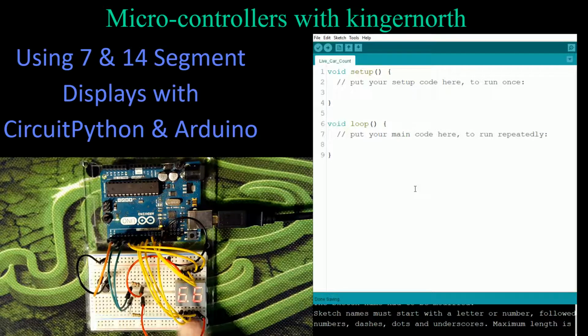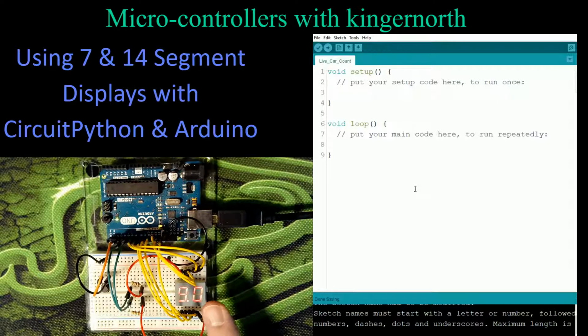And in fact, if you wanted to connect a resistor to every one of these other pins and then use a digit pin, theoretically you could control it. The problem is the current would be too high. So if I had to do the number 8, for instance, all 7 segments of the display would be lit. That's 7 times even 10 milliamps. That's 70 milliamps. That's too much for a pin on the power pin. So you'd have to use a transistor or something else. So we're better off to use the helper file.